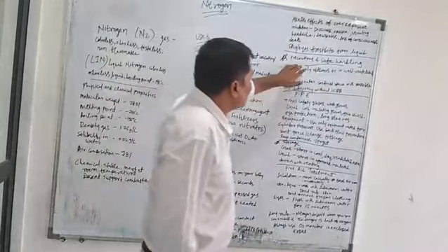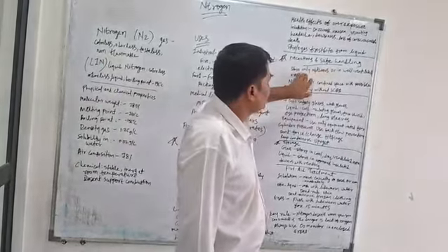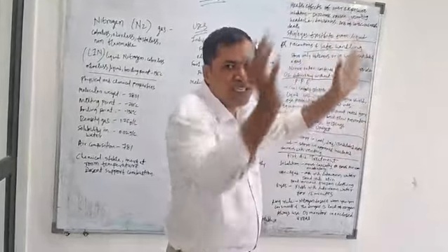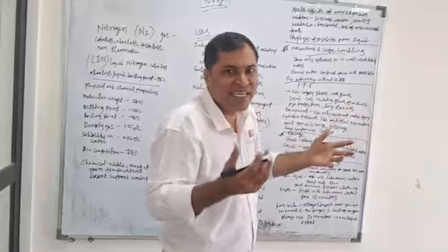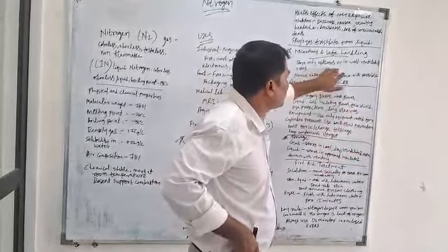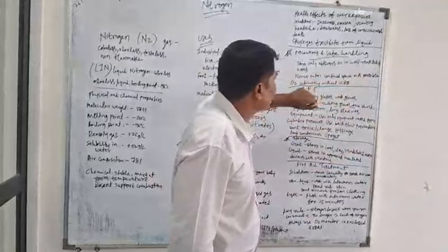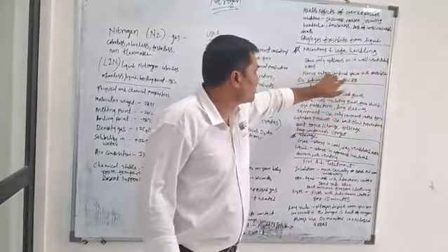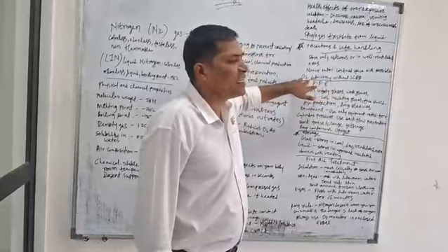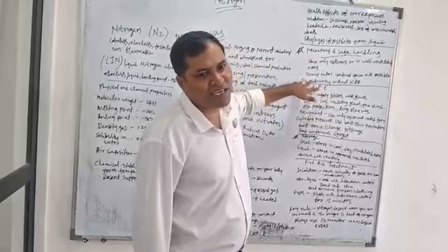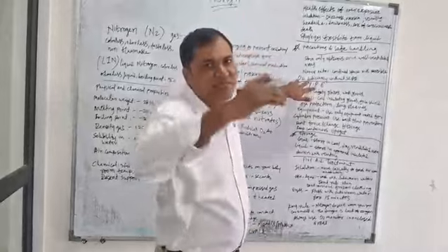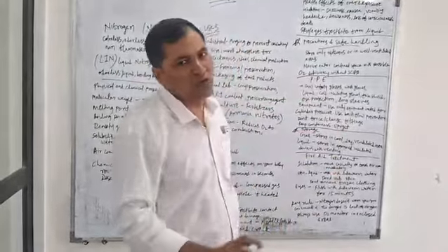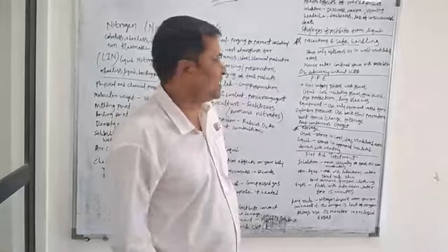Okay. For precaution and safe handling, store only outdoors, never in closed containers. Store in the outdoors or in well ventilated areas. Never enter a confined space if possible. Why never go into a confined space if nitrogen is there at the max limit, the max ppm? Because the oxygen level goes down there. So always go with BA set.